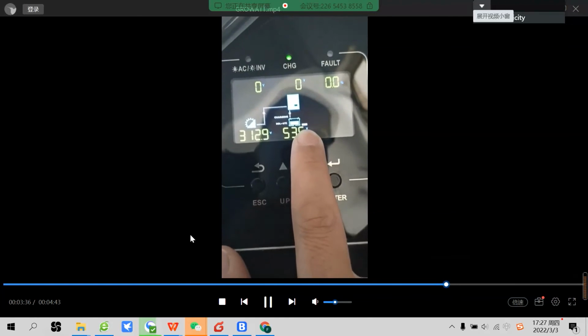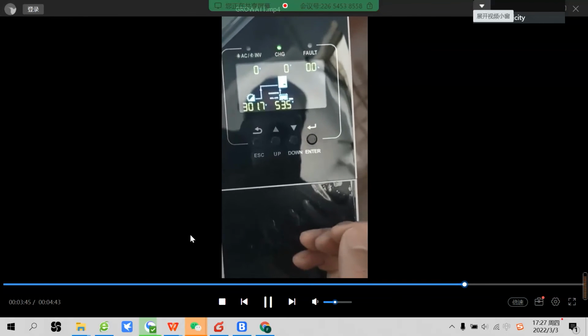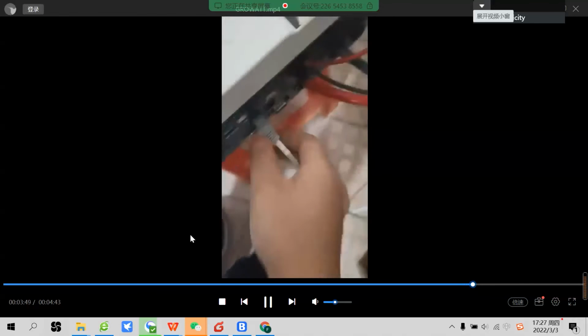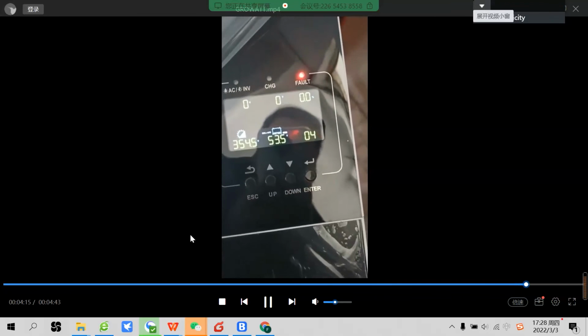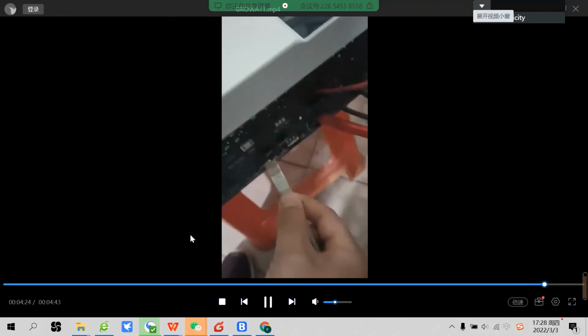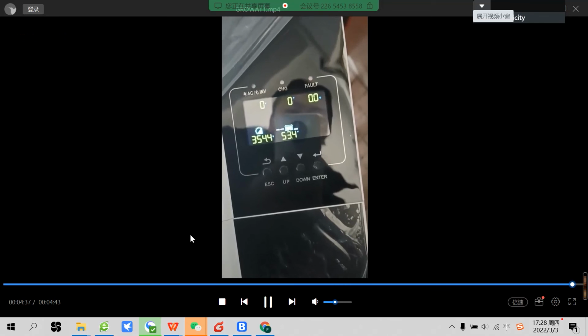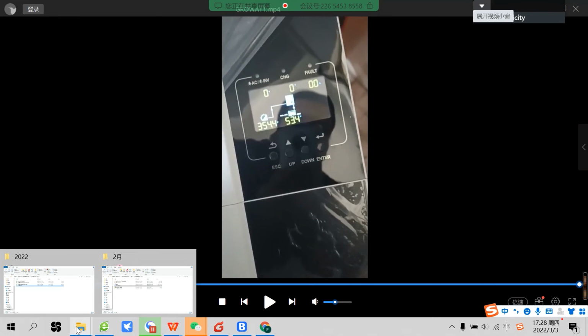But when you connect our batteries to Growatt, you have to connect this cable to the battery with address number one, which means you first connect the inverter with the first battery. This is the test, to check whether there is communication or not. So we unplug the cable, and it shows a communication fault. You will see 04 21, the BMS communication fault. Then we recover the cable, and it disappears. Okay, so this is the Growatt.